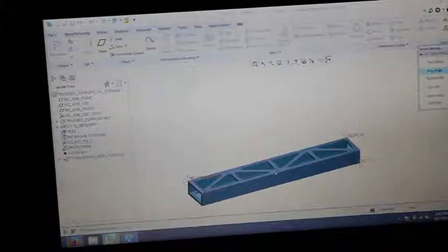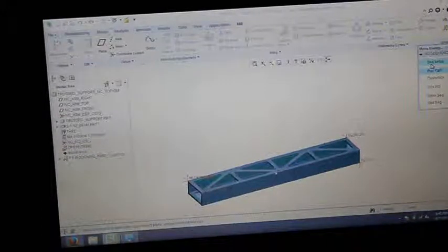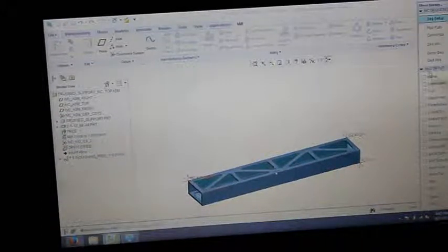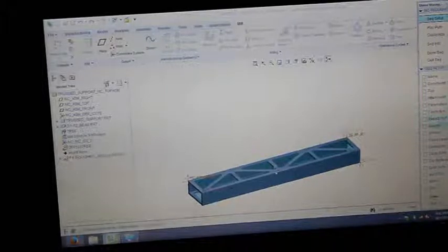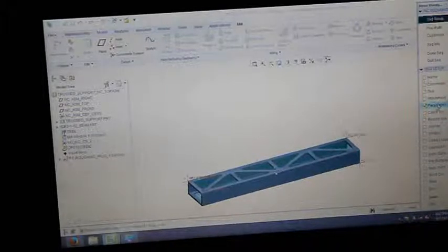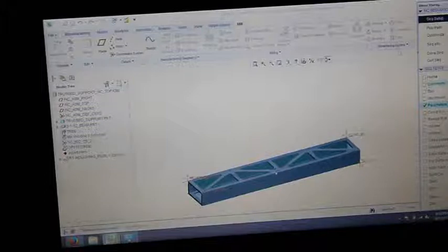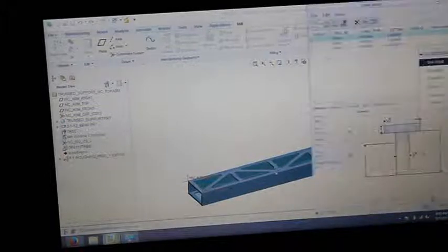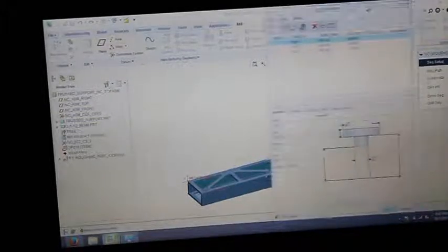This is more complicated, but all you have to do is right-click, Edit Definition, Sequence Setup, and select what you want to change. In this case, we're just going to look at our parameters, and we might as well look at our tool as well. So we hit Done, and it pops up with the tools we have available.